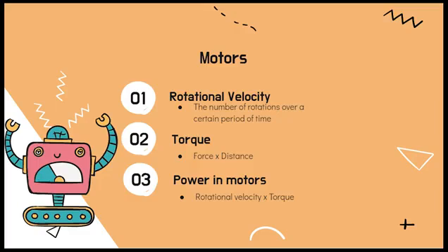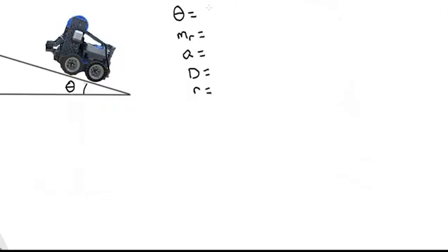The motors in the kit come in different sizes for the students, so one way you can help them gain some problem-solving skills is by helping them pick which size motor they should use for their specific need. Whether you want the robot to move across a flat surface or up an inclined plane is up to you. For the case of the problem, the robot will be moving up an incline of 10 degrees and will weigh approximately 25 pounds or 11.36 kilograms.